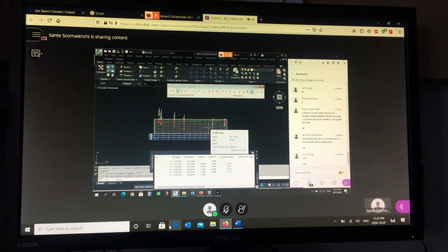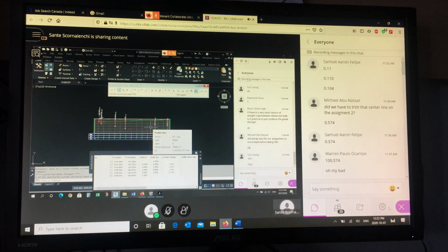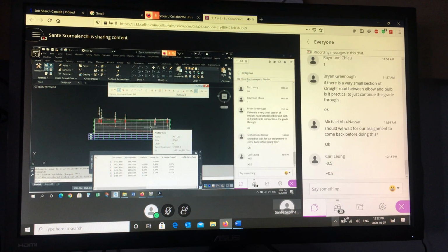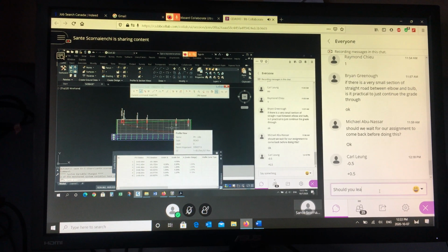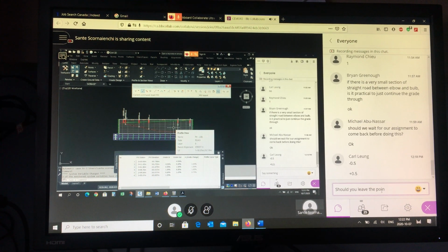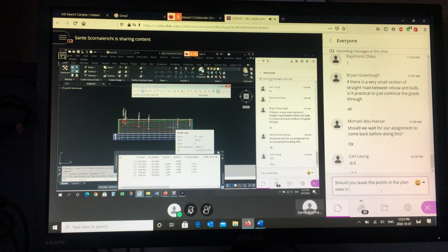That's your homework for next week. If you can get that done for next Tuesday, when I see you next, then we can proceed to cross-section. We're going to look at the assembly with sub-assemblies, and then we're going to build a corridor. And the corridor is the most critical piece of information to do your grading design, and the most critical piece of information to do your servicing design. And you'll see why when we get to it.